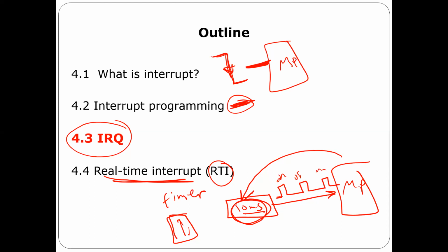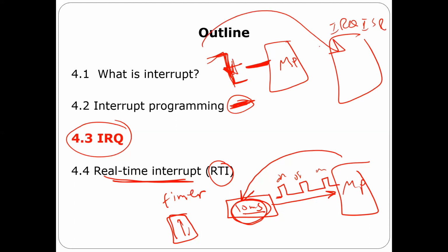So every time there is a falling edge, you trigger an interrupt and you execute a subroutine. That's it. So this is IRQ, interrupt request. Every time there is a falling edge, you execute a subroutine, and so on. Someone can ask me where this falling edge is coming from. It depends on your application, for sure.